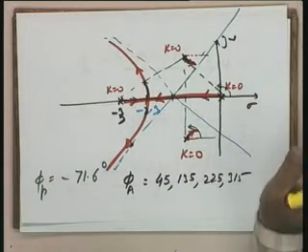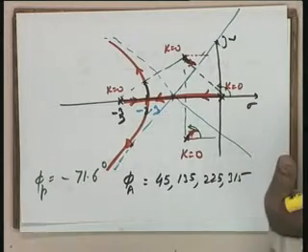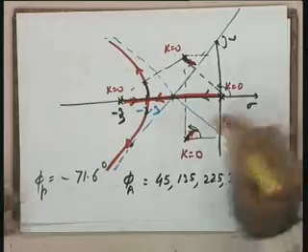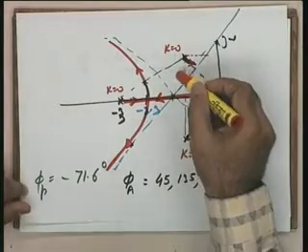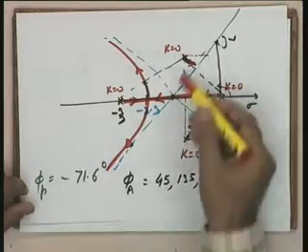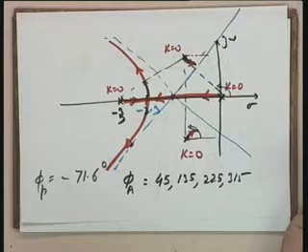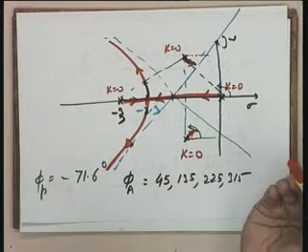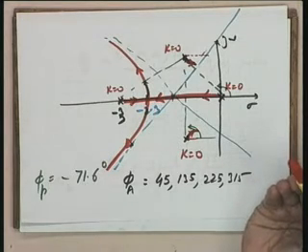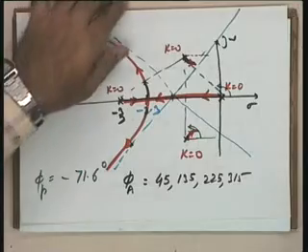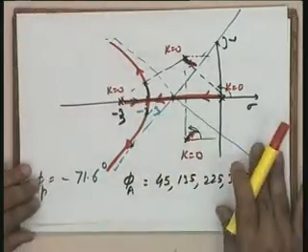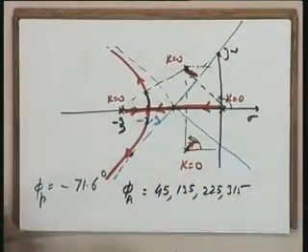After all, the point you have calculated, my intuition says that it won't lie. If you don't agree, quantitative evaluation is possible. Take a point, and because the angle criterion requires all the open loop poles only, take that particular point and apply the angle criterion and satisfy yourself. Okay. Now these root locus 2 branches we have already calculated. Go to the other 2 branches.